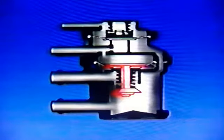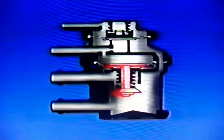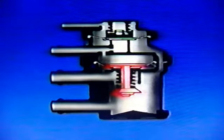The second type of canister control valve is more complicated. It has created many problems in the past because it has a tendency to suck fuel out of the carburetor. This type of control valve uses PCV vacuum to purge the canister. And as you can see in the diagram, it has two diaphragms operating the valve assembly. If the lower diaphragm ruptures, the strong PCV vacuum will cause raw fuel to be drawn right out of the carburetor. That's why when working with this type of canister control, it's better to remove the canister hose and the PCV vacuum hose, then plug the PCV hose.